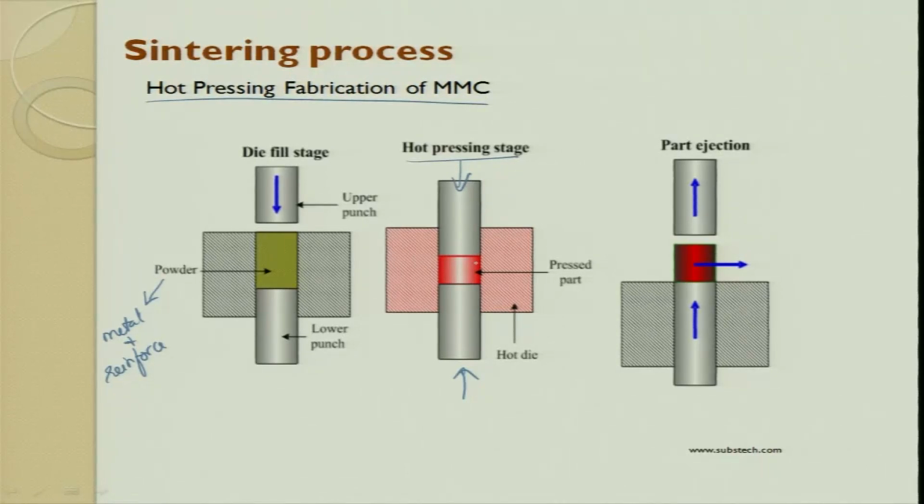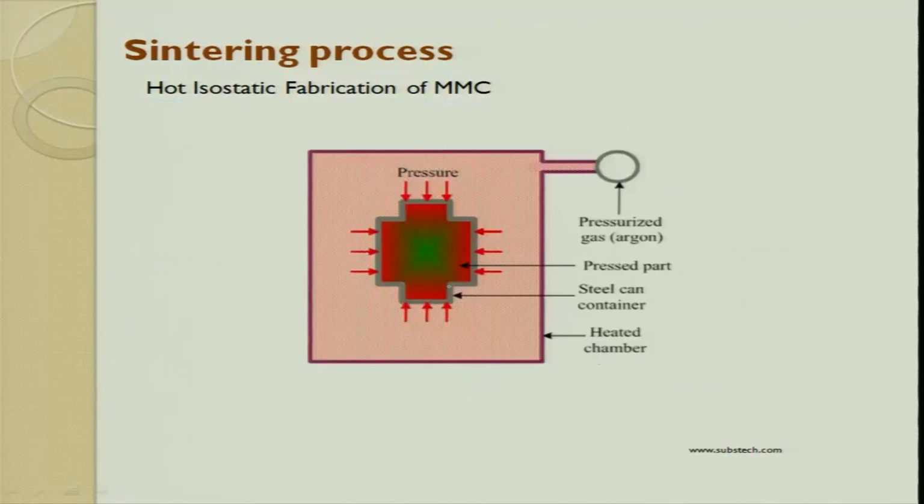If you do not do proper mixing, then you might have cracks inside, which are very difficult for you to visualize. I am talking not about the surface, but the cracks inside. So, this will lead to poor quality output.